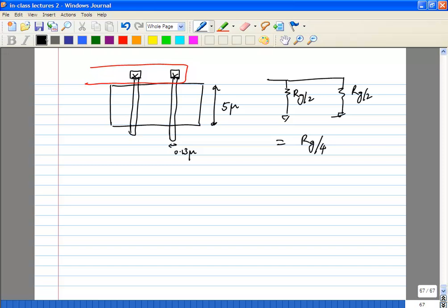I'm assuming that all your designs will be less sensitive to capacitive parasitics because you're tuning. We'll consider it probably in one class at the end. I'll have a layout class where I'll go over many of these effects. I just wanted to give you this so that you don't end up doing a design where you compute your noise figure and suddenly see that a lot of noise is coming from the gate resistance of the transistor, and you won't know how to reduce it. So just try to keep these little things in mind: don't have the finger width less than 1 micron, not larger than 5 microns.